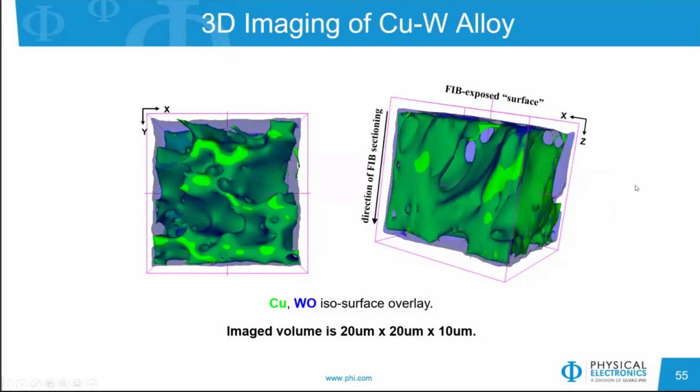you can just really see how they're mixed here. And this information might have been lost doing a traditional depth profile, because you can have preferential sputtering between copper and tungsten, or you can get roughening that would disturb the chemical information and how it's distributed in depth. So this FIB-TOF method is a nice way to preserve the information by milling it out and imaging it, and then reconstructing the profile.